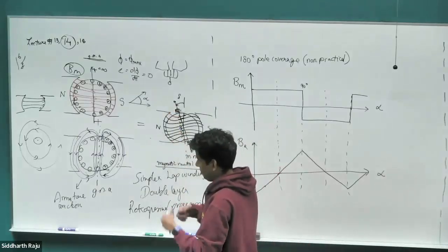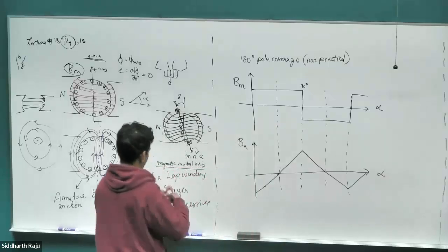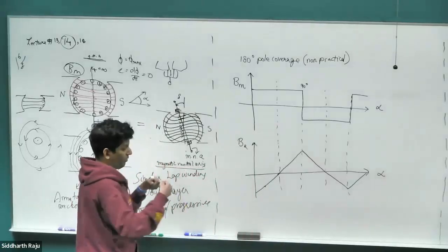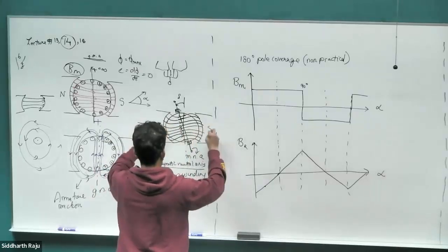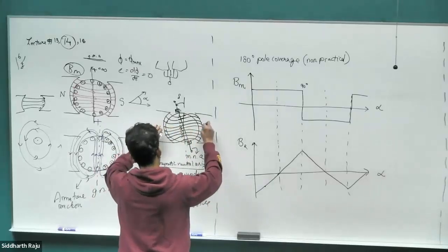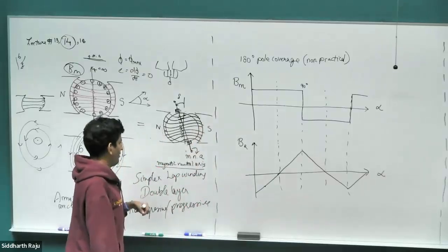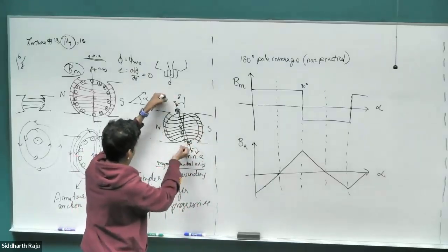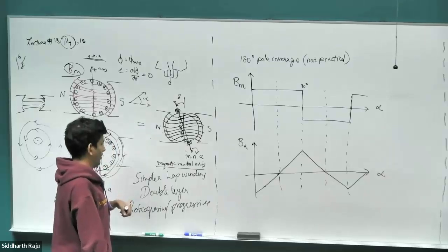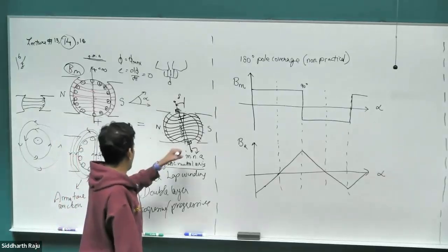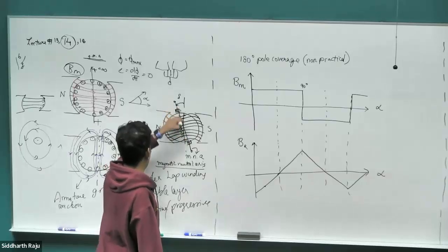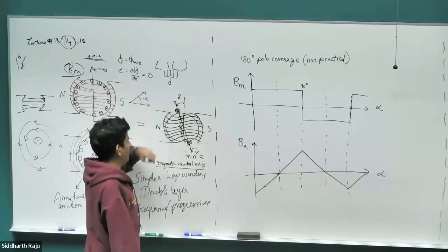Typically, you will see these brushes when you open them up. They won't be exactly where the winding works out, as we saw in the winding diagram. The brushes in the physical motor would actually be along this axis, not exactly at this axis. They would be slightly shifted out, right? So that's basically doing the shifting in this effective equivalent circuit diagram that we're drawing here. Once we have shifted this out, we can ensure again the EMF along this axis, the coil which is along this axis will be zero, so we can short it and get away with it.